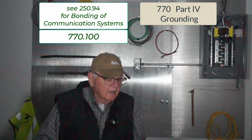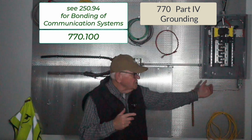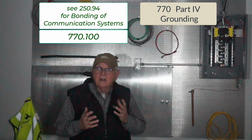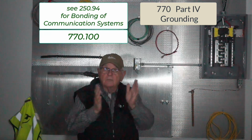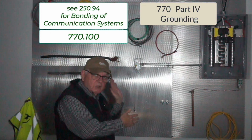Now there are rules. Let's say that my intersystem bonding termination and that intersystem bonding jumper, it works out, they're not close together. Usually we're going to terminate our communication cables at the demarcation point, we call it, where the utility connects to our premises communication wiring. That's going to be close to the service somewhere.